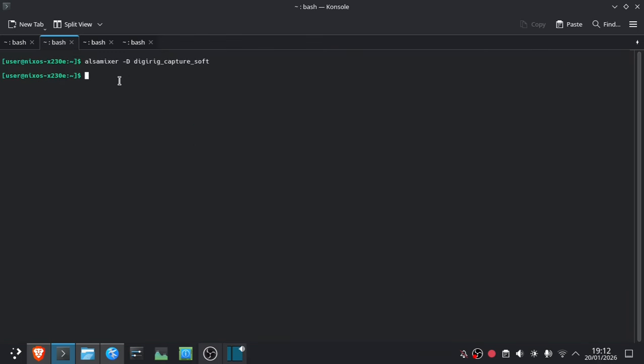So what's the next thing to do? You remember the direwolf was listening on port 8001 for a connection, and the problem is that the program I'm going to use, which is called xastir, if that's how you pronounce it, the APRS transmitter receiver program, can't talk to TCP interfaces, so we need this converter that converts the TCP interface I mentioned into a serial link that looks like this, and then xastir can talk to it.